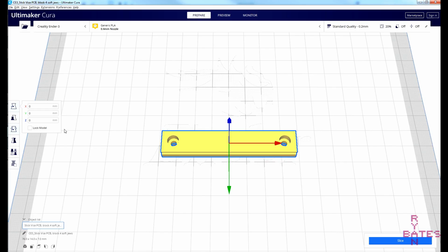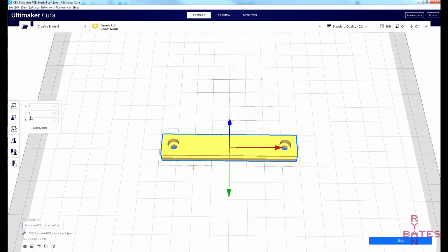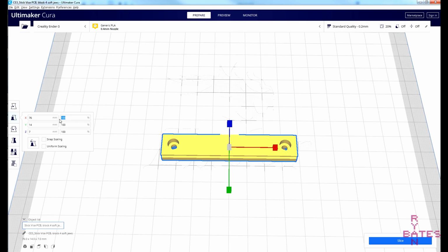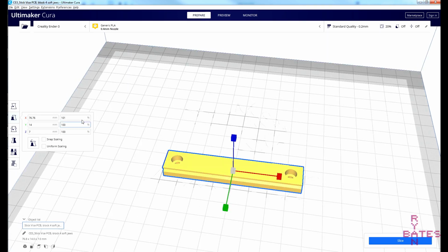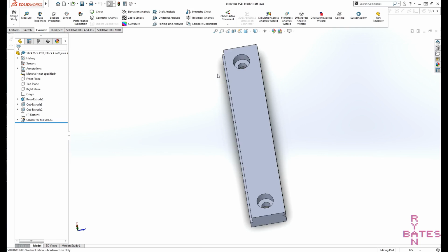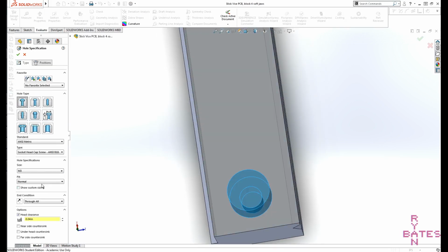to print. You'll find when printing screw holes, mounting brackets, or mating parts, they might not fit as you dimensioned or toleranced. Depending on your CAD design, you can simply scale your model here to compensate for shrinkage. Scaling can be done uniformly, so the same ratio across the X, Y, and Z axes, or just along a selected axis or two where the shrinkage is more prevalent. Knowing this and exercising good design principles will alleviate this one downside to 3D printing.